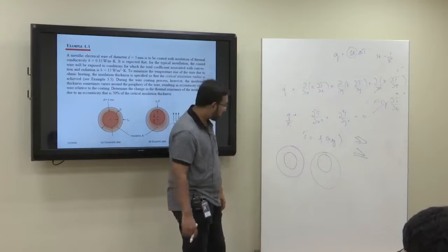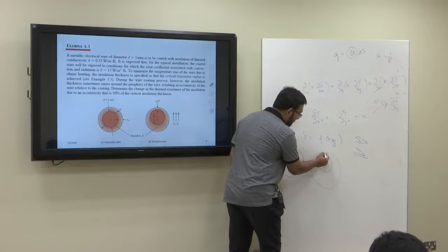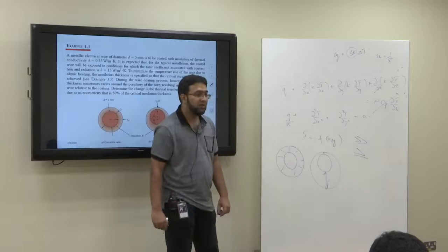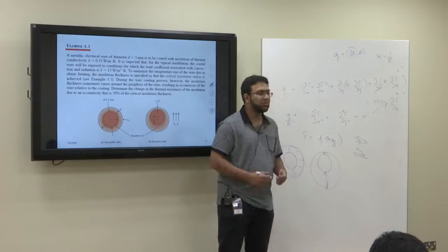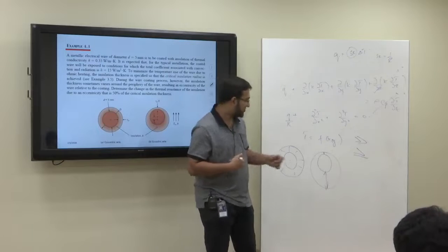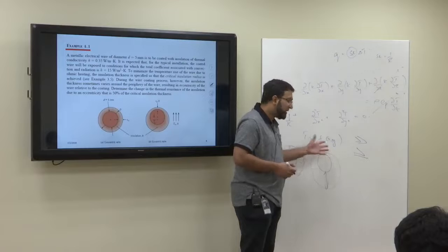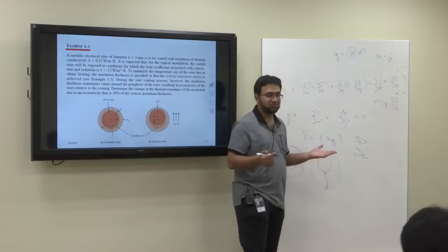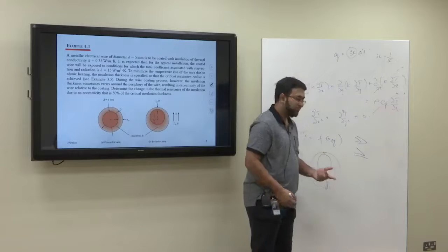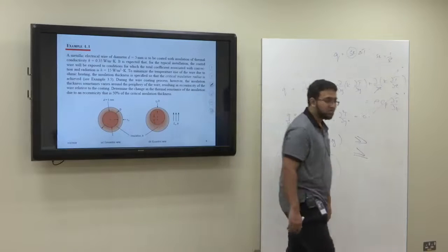In this case, although here the thickness was all the same around, now the thickness here drops and here the thickness rises too much for the insulation. When the thickness rises, that's not a big issue, but when you have a drop in thickness, now there is a problem, because maybe it will become too hot, maybe it will burn, maybe it's not going to provide that much resistance. This insulation thickness is providing the resistance. Now the resistance here has increased, but the resistance here has decreased.